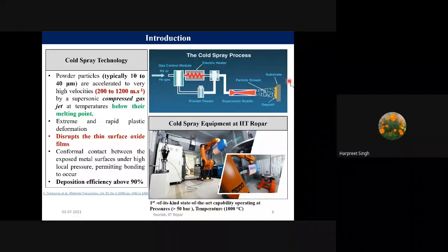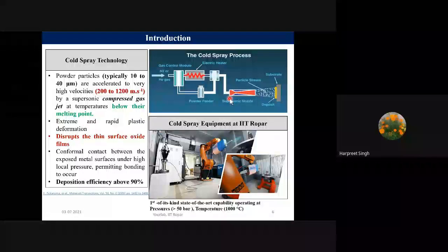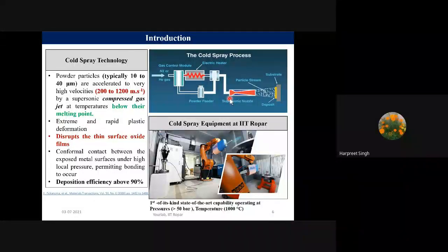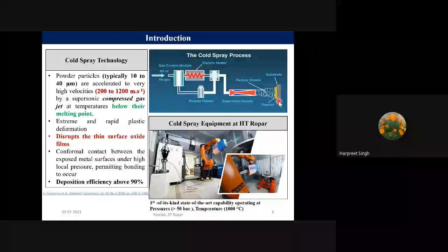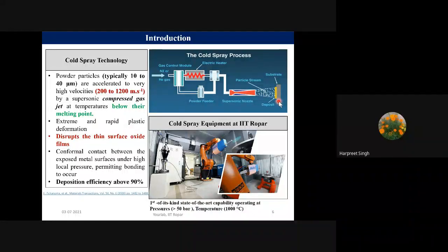The objective here, again, is that we want to deposit this material on the substrate, right? What we do in this cold spray system is propel the particles at very high velocities, so that they go with a very large kinetic energy and impinge on the surface, where they plastically deform and get stuck. It's like converting the whole of this kinetic energy into deformation energy and some heat energy also.